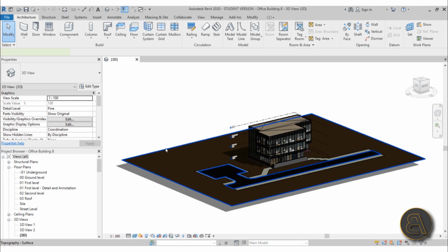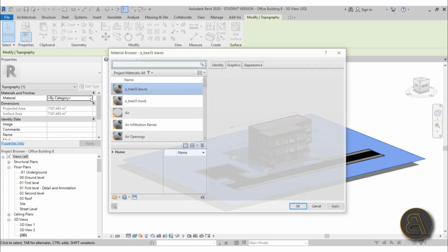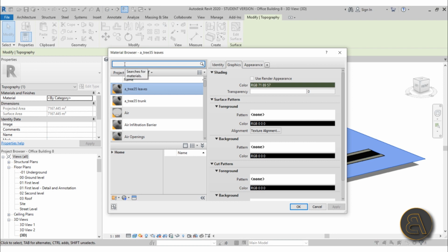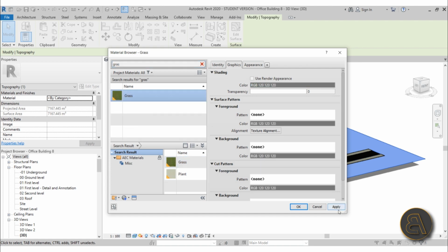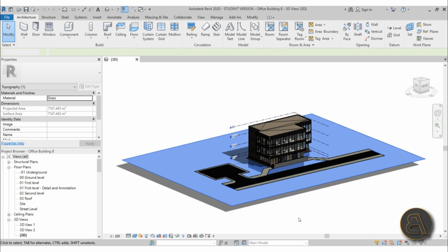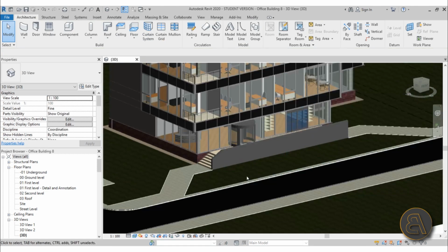Okay, so I have restarted Revit, and now if I select this and go here into material, hopefully it will be working. So if I go here, grass, there we go, now we have grass. That's just a problem that I found that occurs with Revit from time to time, and if it happens, you just restart Revit. I guess you can't just close the project, you should probably restart Revit altogether. Okay, let's load in this grass material, hit apply, okay. And there we go, looks much nicer and greener, and I actually really like the look.